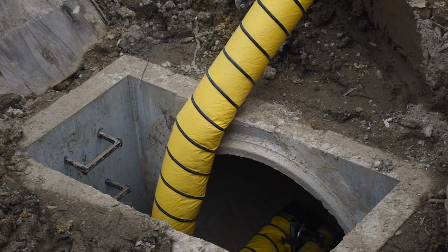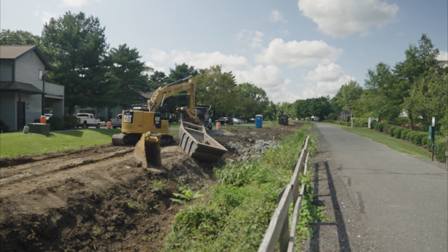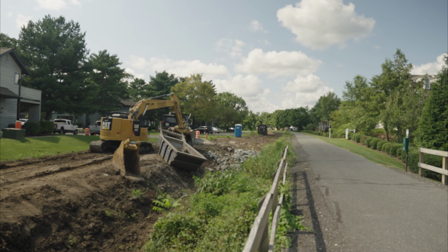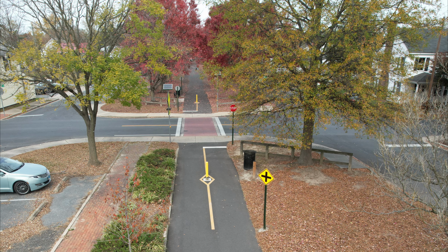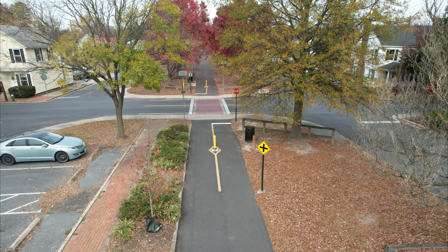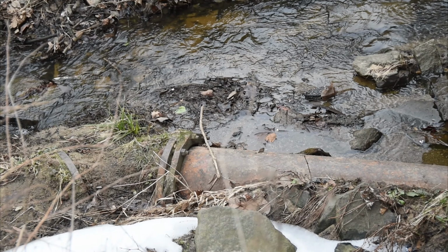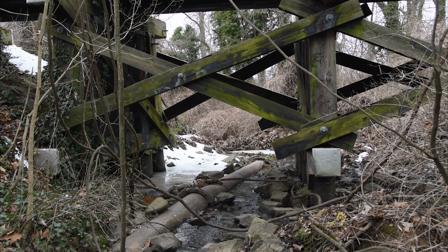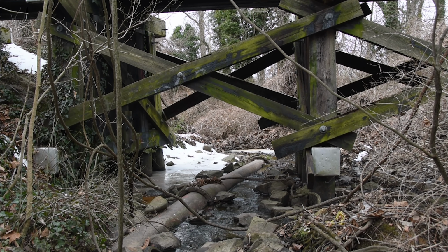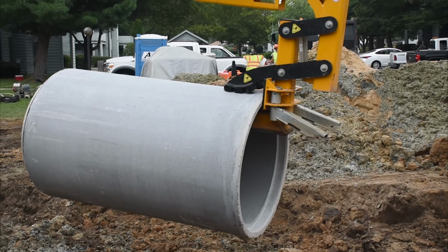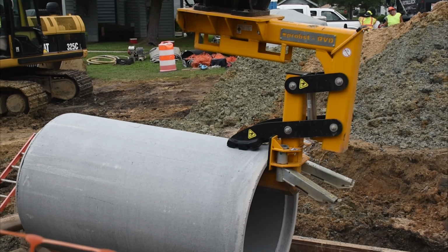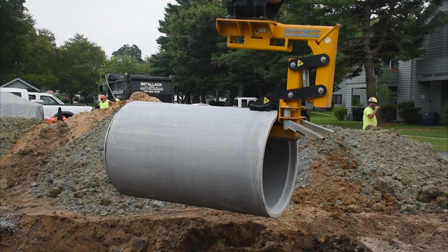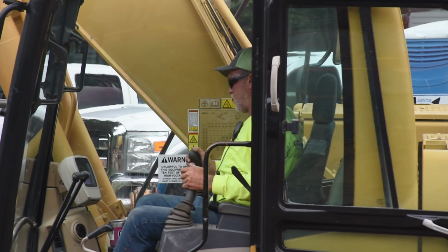These constraints included the need to connect to the existing storm drain network, maintain enough fall or slope to convey the water, and to be deep enough to miss existing underground utilities. While some of the existing underground utilities, such as water and gas mains, could be relocated at an expense if necessary, the sanitary sewer system cannot be relocated. Since it is a gravity-driven system, there was no flexibility to go up and over to avoid the new storm drain system.